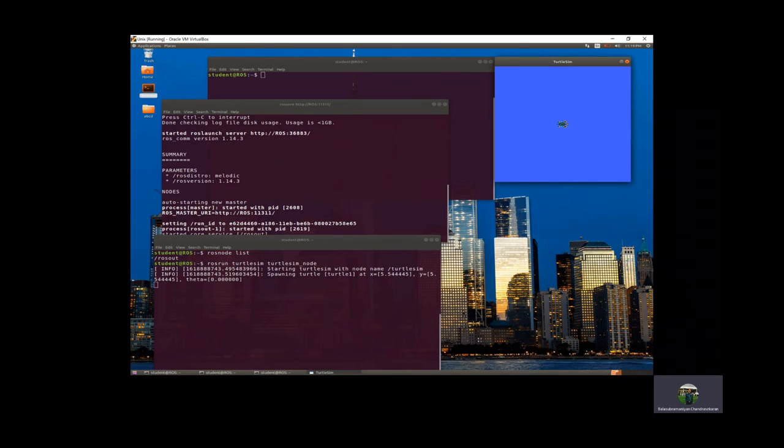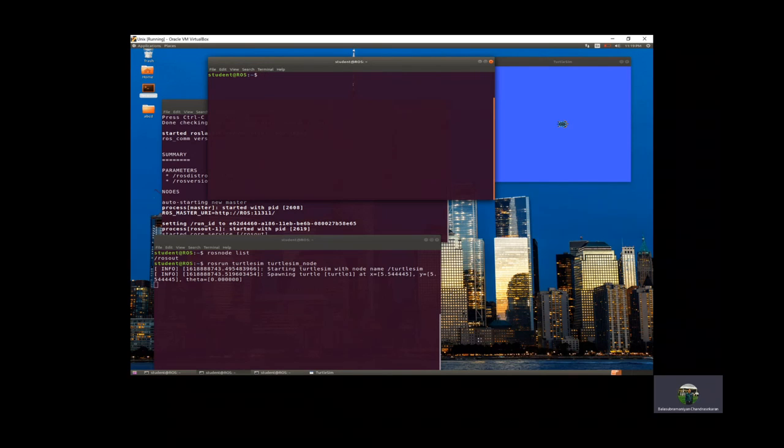Now the purpose of this module is that you create a robot like a turtle, and then we can control it. To create the turtle itself is one node, but to control it we need another node. Okay, so again we have to use ROS run. ROS run will be the command followed by the same package, so it will be under the TurtleSim.